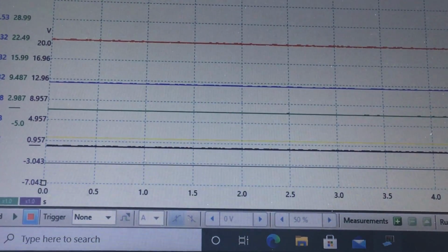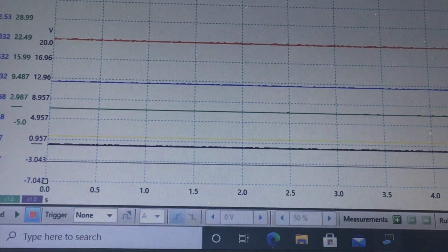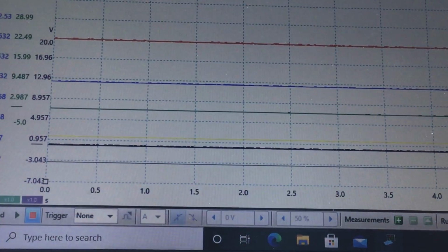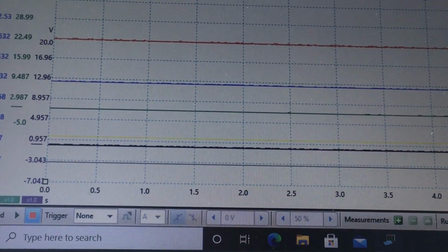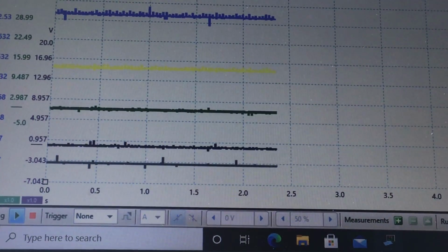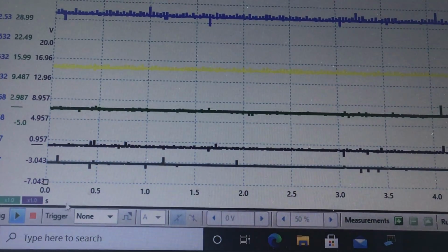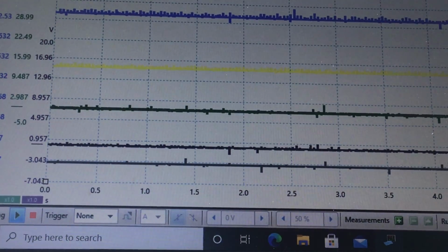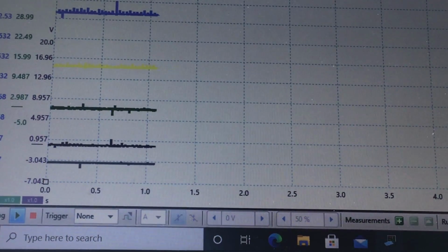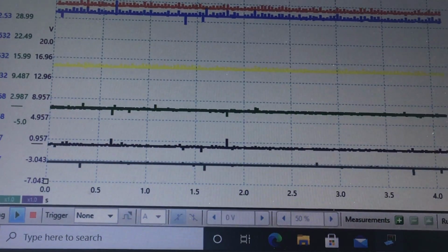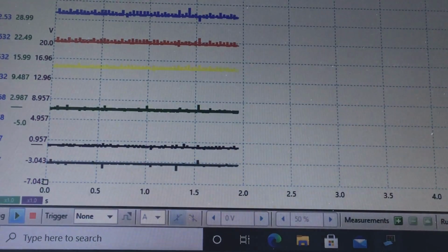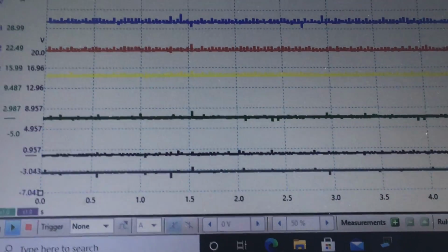So I'm cranking the car up. Let's start the scope. Okay. We're missing somebody. The red guy should mirror the blue guy. This is when the blower motor is off. Right now we're going across the screen. The car is running. The blower motor is off.